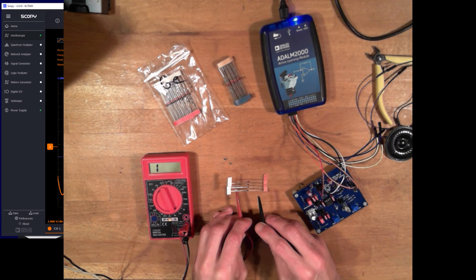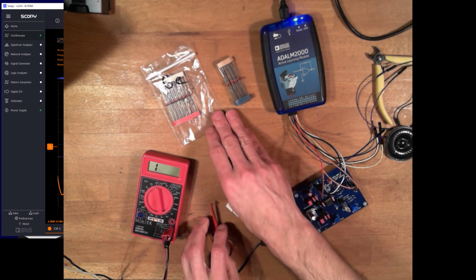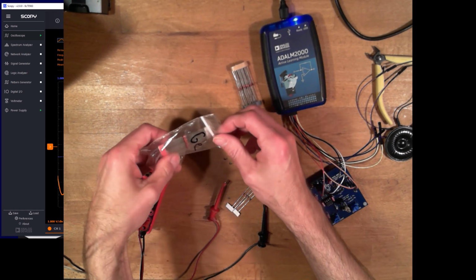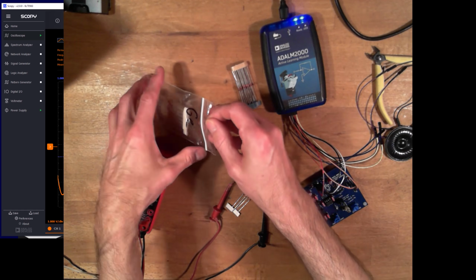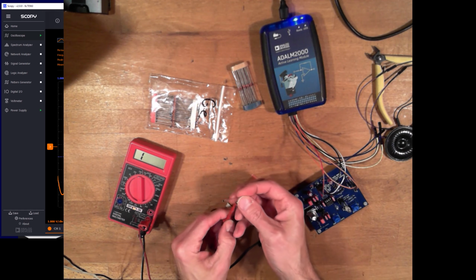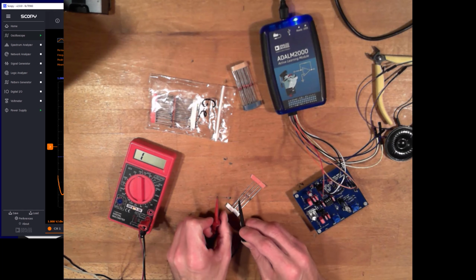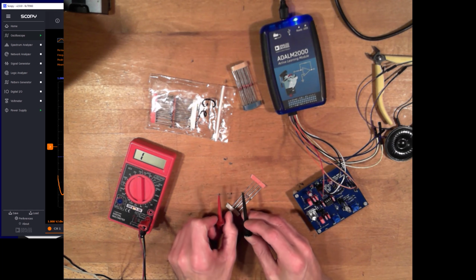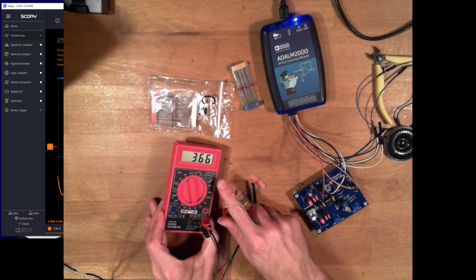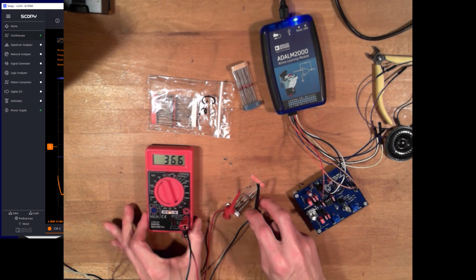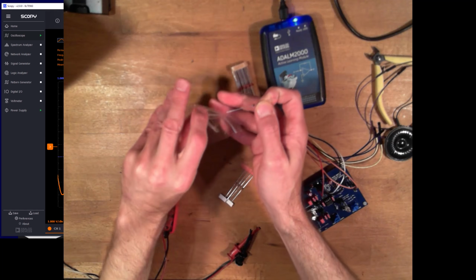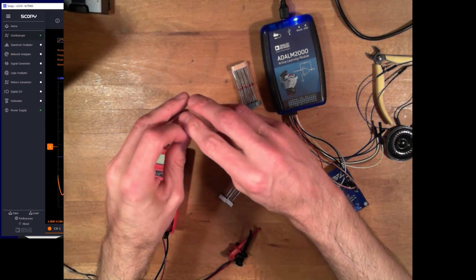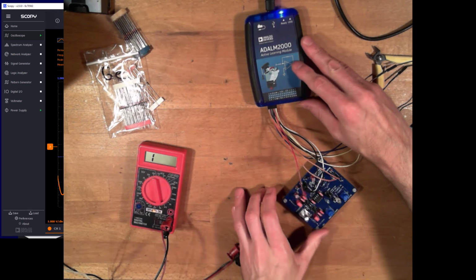And also, just for fun, I didn't solder this in, but another alternative would have been to use a germanium diode. So I've got a bag of germanium diodes here, and similarly, these guys have a considerably smaller forward drop than a silicon diode. Yeah, so about 360 millivolts, so somewhere in between. Okay, so let's take some measurements with this setup here. Get these guys out of the way.